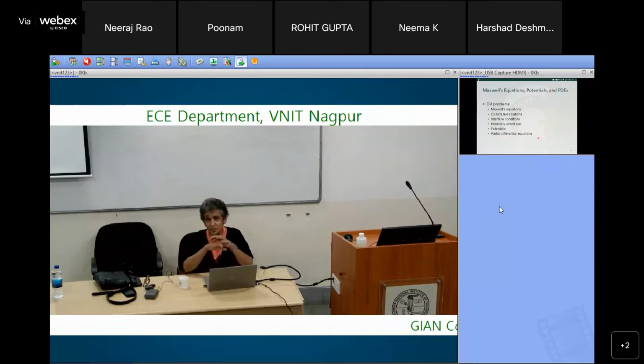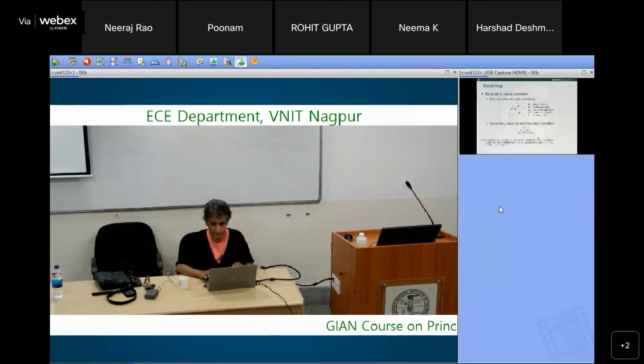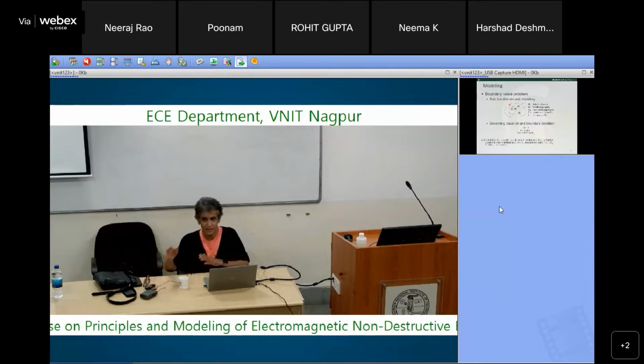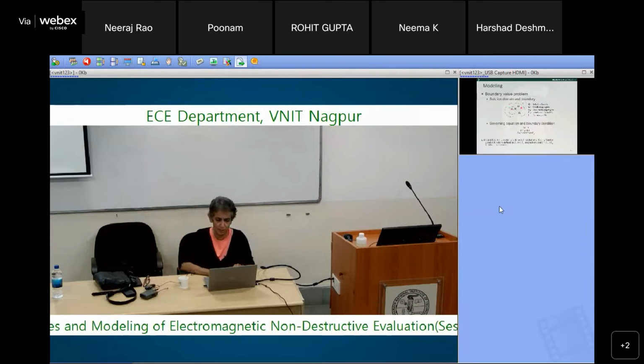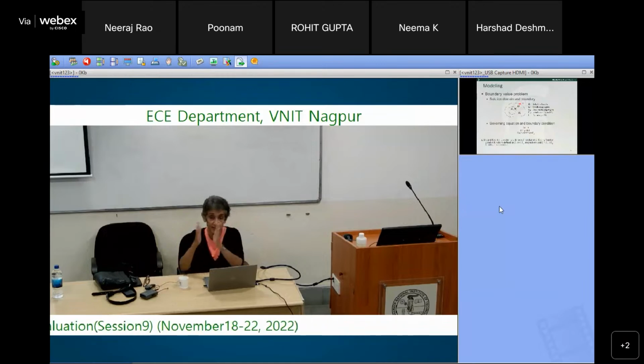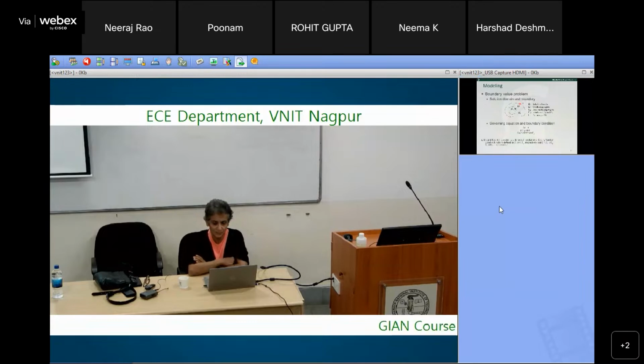Boundary conditions are typically on the outer boundary, where you can apply some kind of condition. If it's static, I can apply homogeneous Dirichlet, so everything is zero. That's the outer boundary. The interface is in between. You have two different materials. So if you have layered structures, for example, in between there's an interface. If I have a conducting and a non-conducting region, then I know what happens: I can't have a normal component of the current density vector. So those would be the interface conditions. Okay.